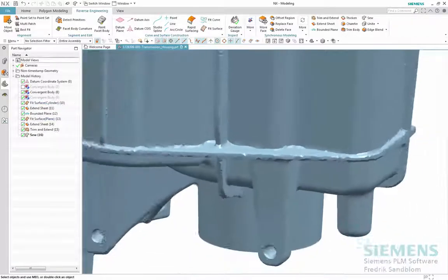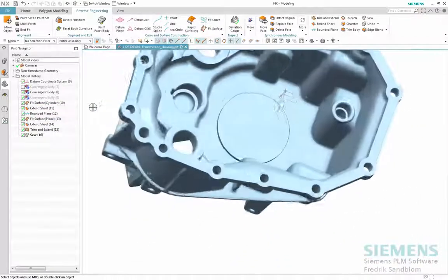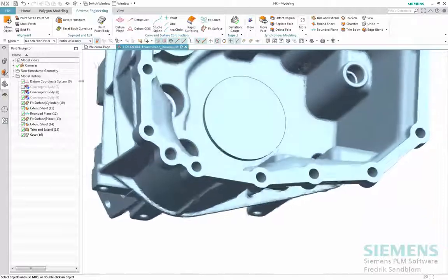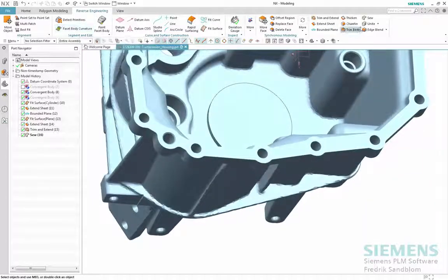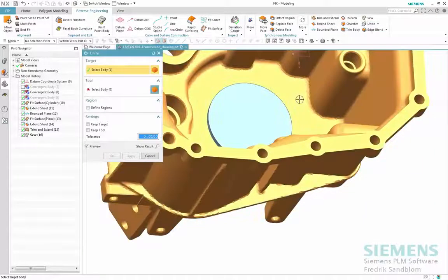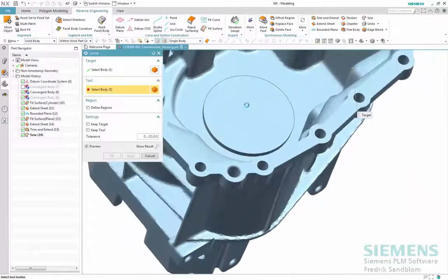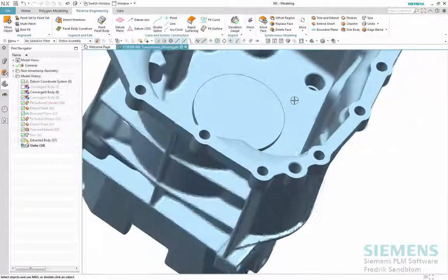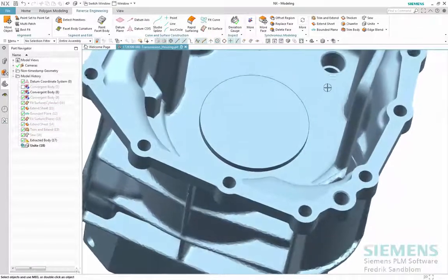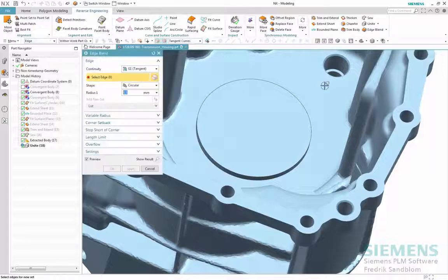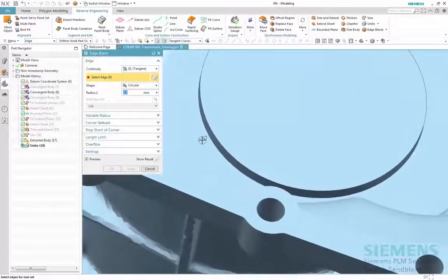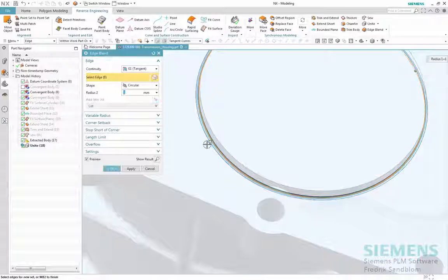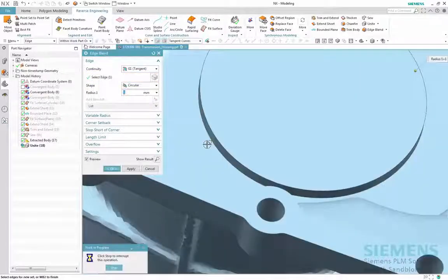We unhide the convergent base body and unite the two solids. Note that the just created traditional analytic solid cylinder will be united with the convergent base solid body. Also note the really cool thing that you can add a regular blend feature to the resulting edge, and the result is parametric. As you probably already are thinking, this enables process automation.